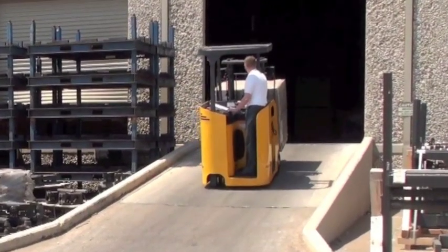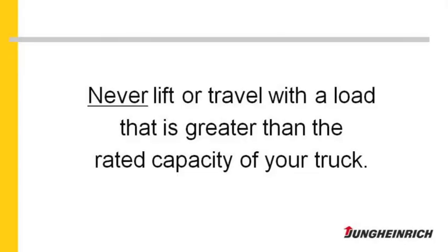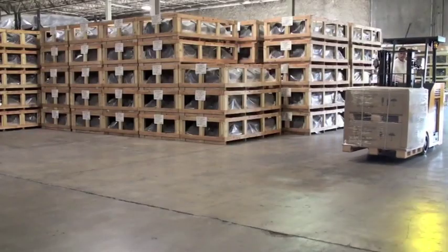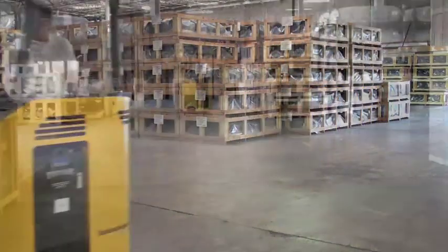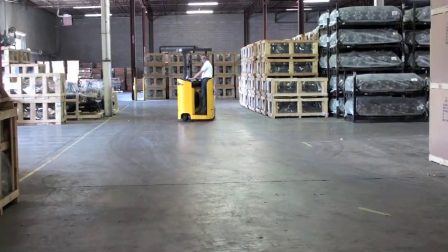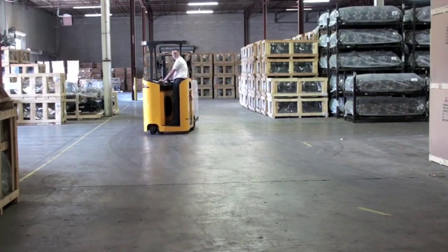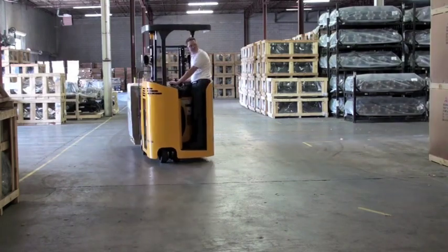Avoid these situations and never lift or travel with a load that is greater than the rated capacity of your truck. Remember, it is your responsibility to maintain the center of gravity within the confines of the stability pyramid. By keeping your maneuvers smooth and slow, you will minimize the chances of losing stability and creating a tip-over.